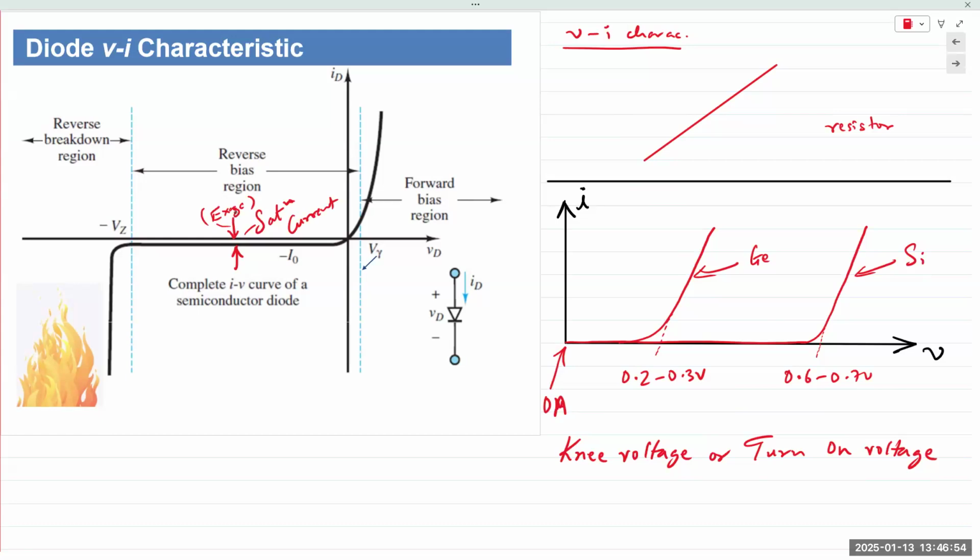All right. So if you forward bias a diode and you cross 0.6 to 0.7 volts, current is allowed to flow through. A large amount of current flows through for a small increase in voltage. In reverse bias, it's going to remain zero for a long time. You keep increasing the voltage, 10 volts, 20 volts, 25, 30, 40, 50. After a while, sufficient energy is imparted into the carriers that the depletion region width does not matter. They acquire enough energy that they're going to cross over the junction, resulting in a large current flowing through the junction. And so that is known as the breakdown.